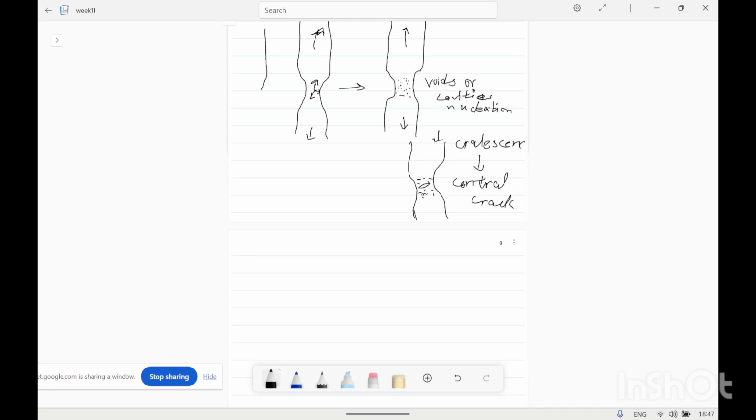As the crack starts to propagate along the 45-degree angle because of the shear stress generation in this necking region, it will start to propagate and form a large void, a large crack that will lead to the final fracture of a cup and cone type.